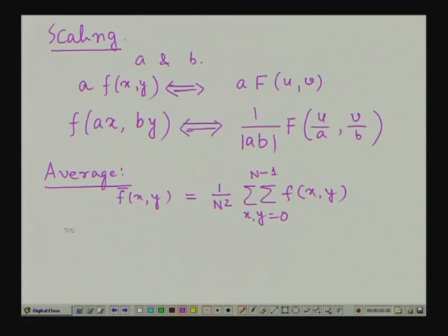Now, find that for the Fourier coefficient, the transform coefficient say F(0,0), what is this coefficient? This is nothing but 1 upon capital N, then the double summation of f(x,y), because all the exponential terms will lead to a value 1, and this summation has to be taken for x and y varying from 0 to capital N minus 1.